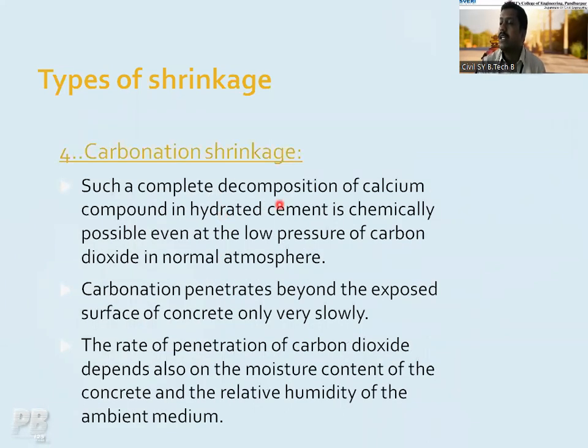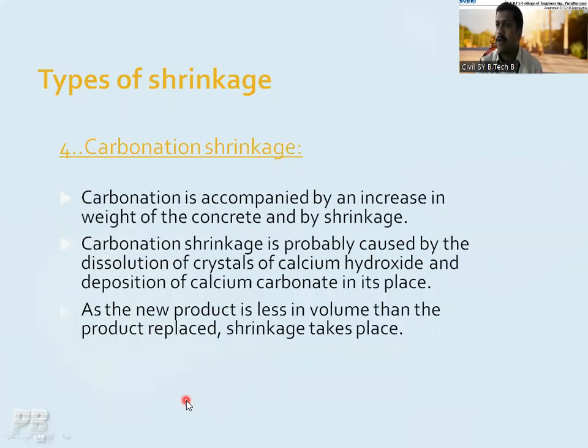Such a complete decomposition of the calcium compounds in the hydrated cement is chemically possible even at low pressure of the carbon dioxide in the normal atmosphere. So the carbonation penetration beyond the exposed surface of the concrete is only very slow. The rate of penetration of the carbon dioxide depends upon the moisture content of the concrete and the relative humidity of the ambient medium. Okay.